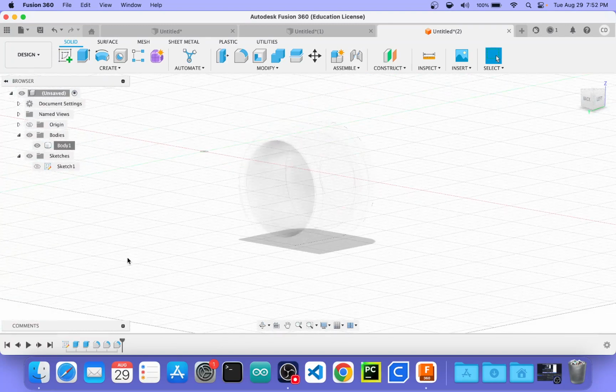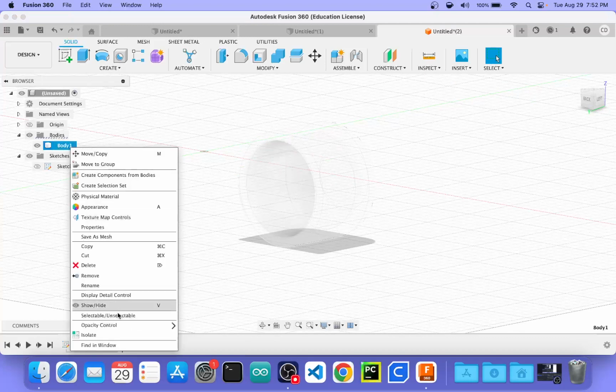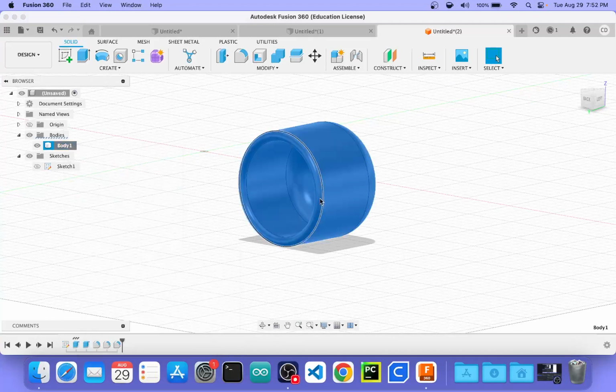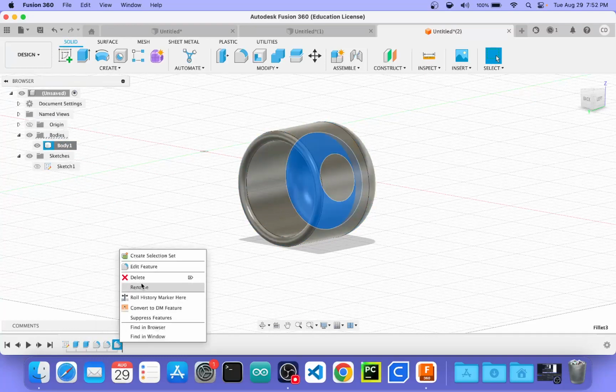And we learned how to apply operations to multiple faces or edges at once, which can frequently be a time saver, especially when you're doing filleting, because filleting is something that you frequently do to a lot of different surfaces. I'll say one more thing about the multi-select application of things like fillets: it creates one operation in the timeline. So if I wanted to change both of these together, I now just have to do that once, right? I could have done these two fillets, so I'm actually going to delete these.